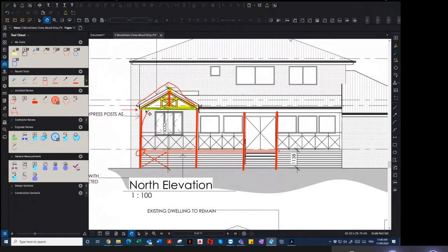And your step bracing is not effective when it goes across because you can't get that tension to happen. And if you tension a lot, you tend to put a lot of pressure on the ridge. If you can imagine, you fix something on this end, and you fix it on that end, and the tension is in the middle.